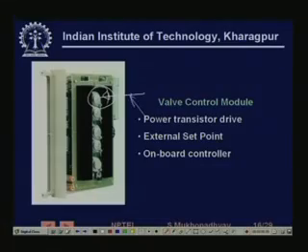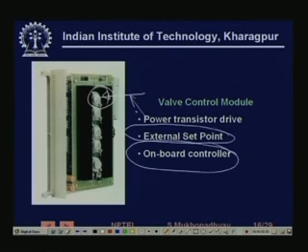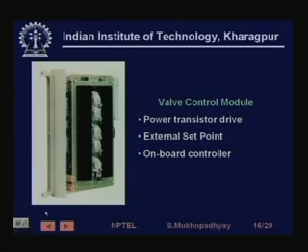For that it needs to provide a good amount of current, so these are the power transistor drives. It takes a set point from outside, so it interfaces to the bus, and the central processor gives it the set point, and it has its own onboard controller. So this is a typical valve module.